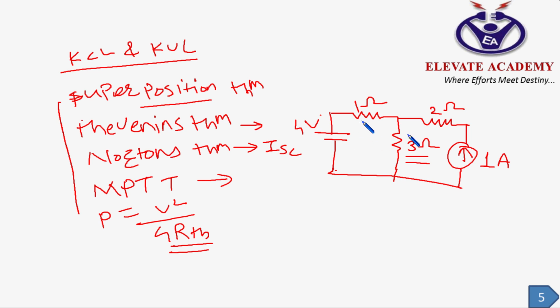That thumb rule is nothing but apply the clockwise direction and find out the 2 unknown currents flowing in the circuit. But logically, in this problem a current source is given to you. A current source is given, which means the second loop's current is already given. I2 is equal to -1 ampere if I am considering the clockwise direction.